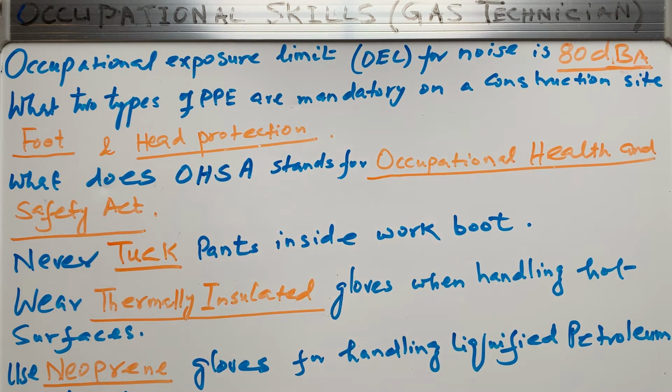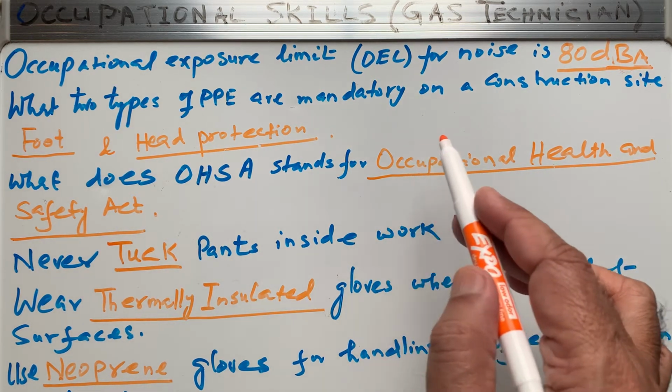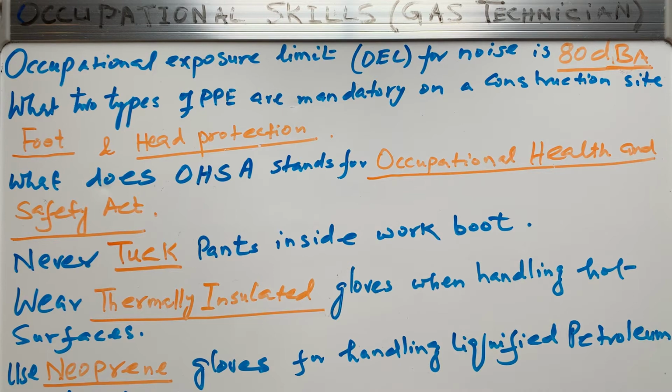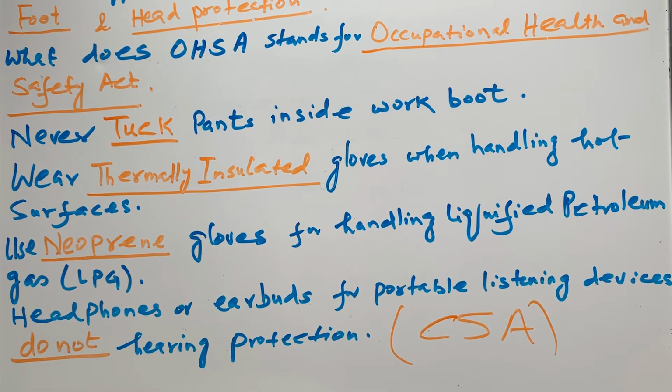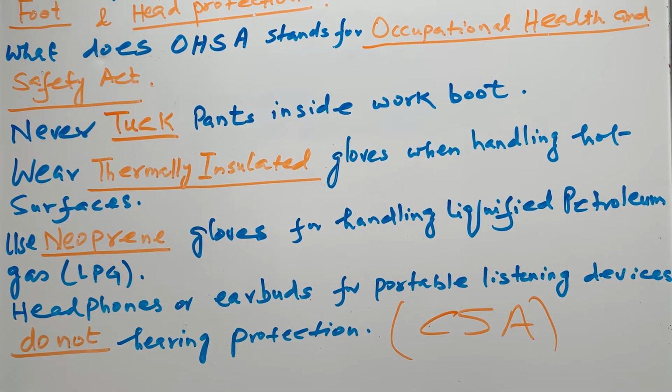And here in Canada, we have to have safety boots with the standard which we call the Canadian standard, CSA. So all boots have a CSA symbol, Canadian Standard Approved boots, which are steel toe and shank. So that steel has to go not only to the toe, but also protect our shank. So there is a green triangle mark and CSA on the outside. The green triangle mark and the CSA sticker must be there. So these are the few things which we need to see on the safety boot before going to the job site.